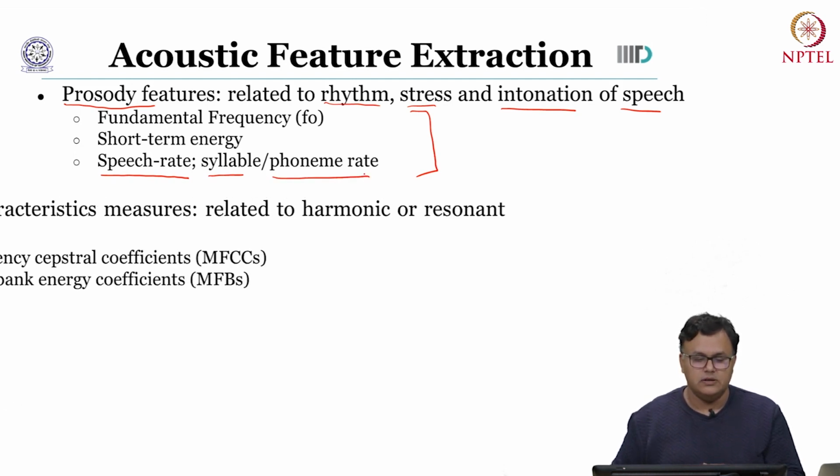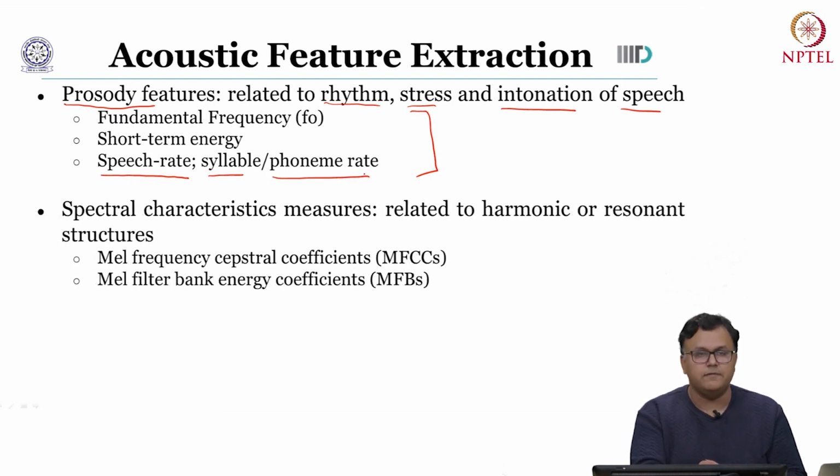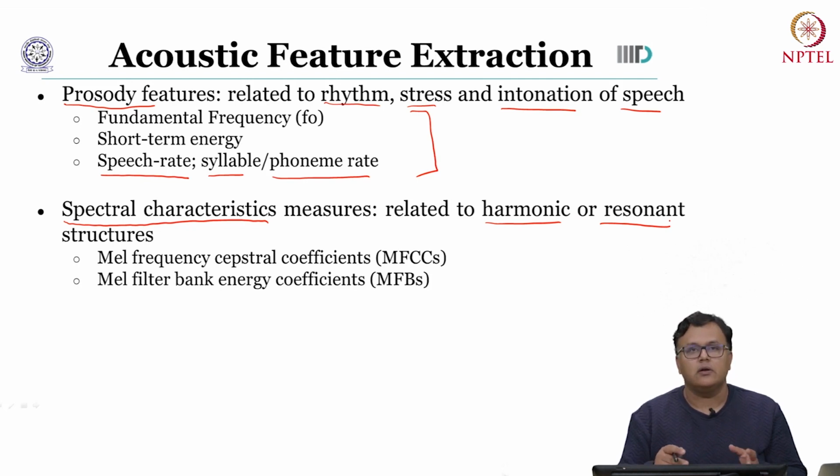Now along with this, we also have features for speech analysis based on the measurement of the spectral characteristics of the input speech. These are related to the harmonic or resonant structures, and commonly these are based on your Mel frequency cepstral coefficients, the MFCCs, and the Mel filter bank energy coefficients.